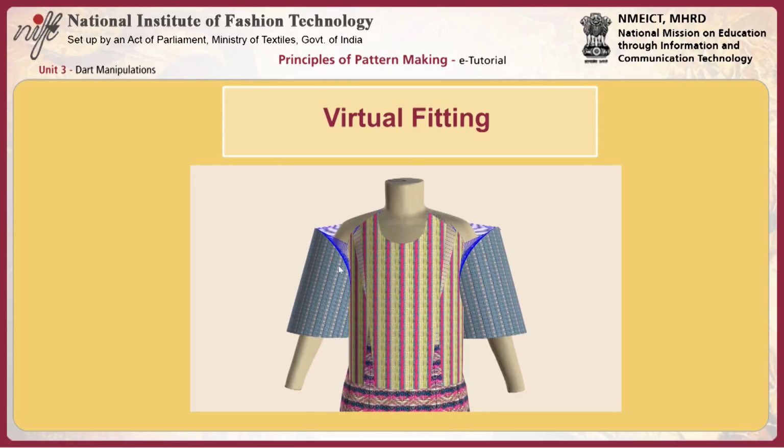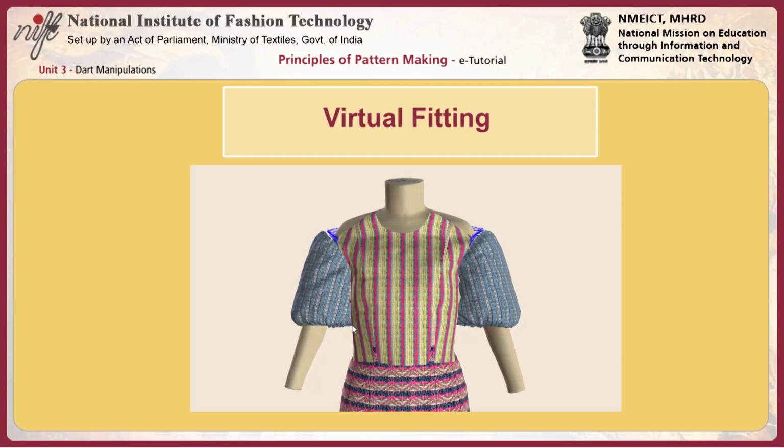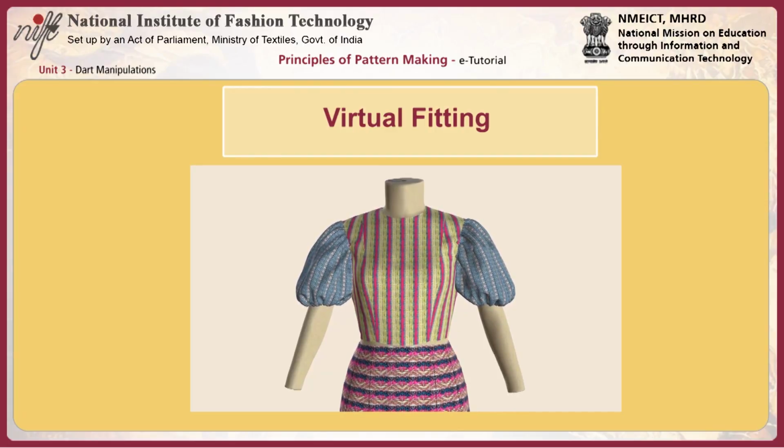Virtual fitting also shows the 3D simulation of how the 2-dimensional patterns are converted to 3-dimensional shape after stitching. Generally, each part of the garment is rendered with different fabric to differentiate the various garment parts. Proper stitching details such as single needle lock stitch on the dots are also given to get the better visualization. This 3D simulation is done on different positions. This will help you get better understanding of the fitting.